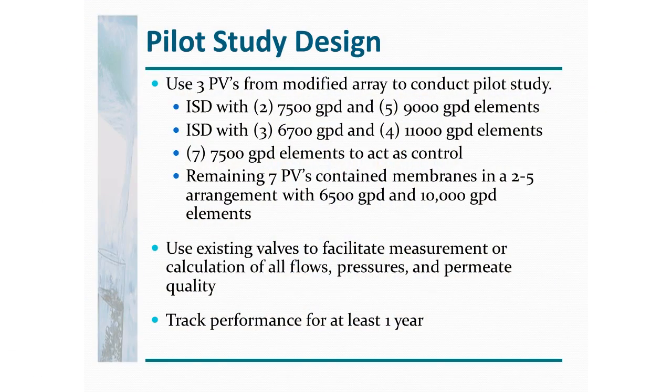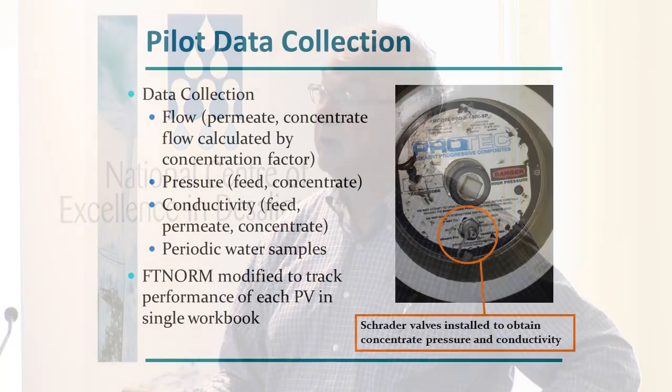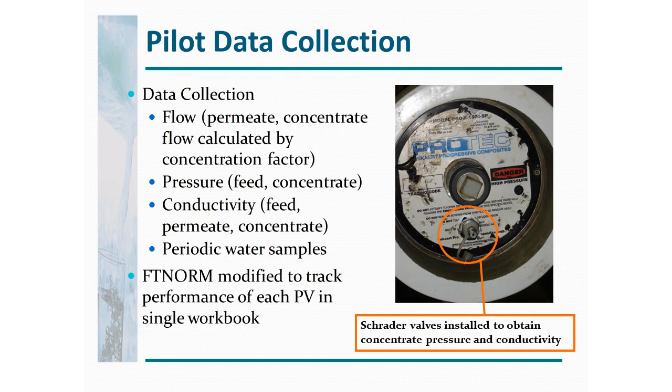But the thing is that you can control the biofouling, okay, with the ISD. It's called ISD, Internal Stage Design. Various companies do this. Dow, Hydranautics do it. They do it for energy purposes because of using these high permeable membranes. But it turns out it works in terms of control of biofouling because the low flux and high cross-flow velocities on the lead end element control the biofouling.